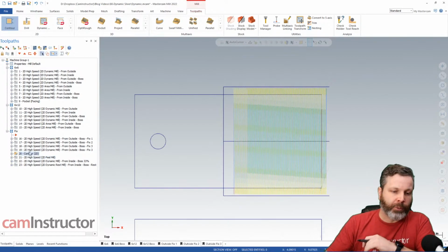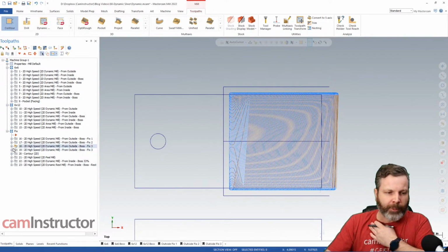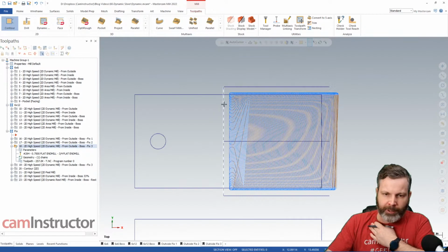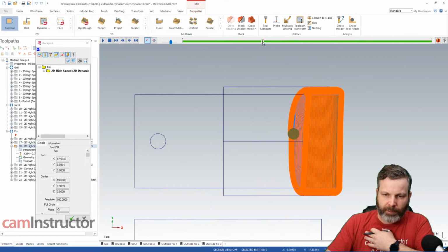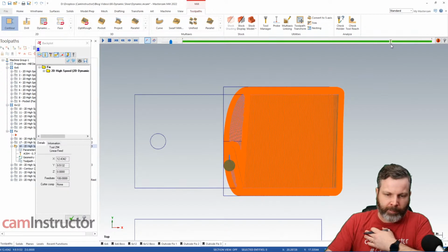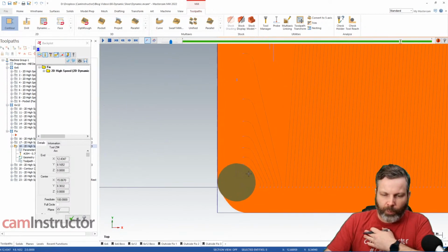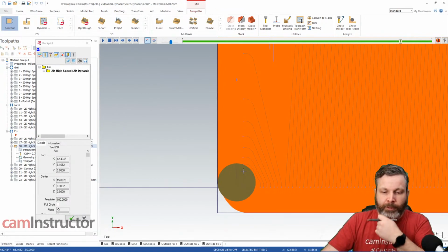We can also do, so this guy here is doing a dynamic mill. Again, I've created additional geometry to create a section that I can get dynamic mill to cut half of the shape. Problem with this strategy, so this toolpath right here is nice, okay? Nice big long arcs, nice consistent engagement angle until we get to that right there. So that right there, we're getting into small arcs, the scenario we're about to get into and talk about with the from inside strategy.